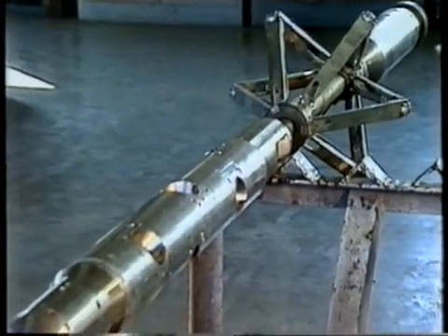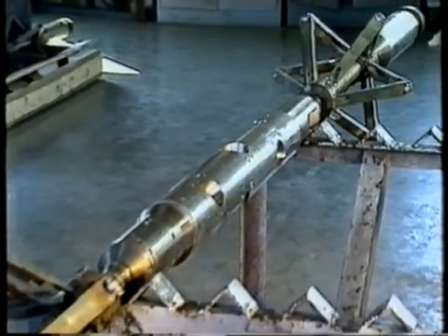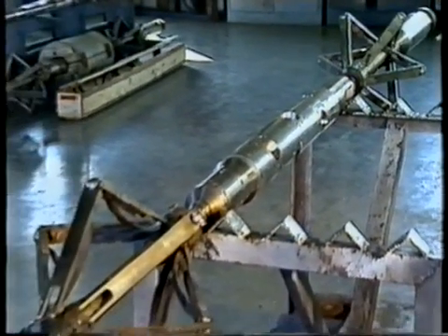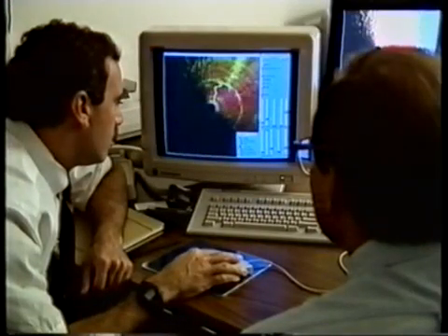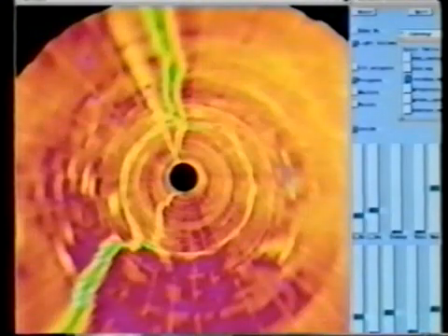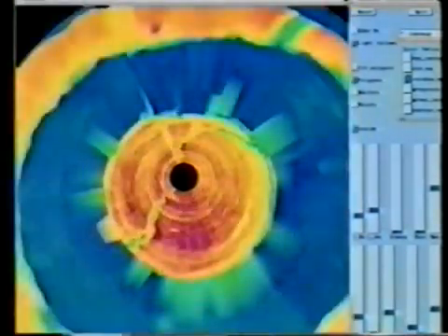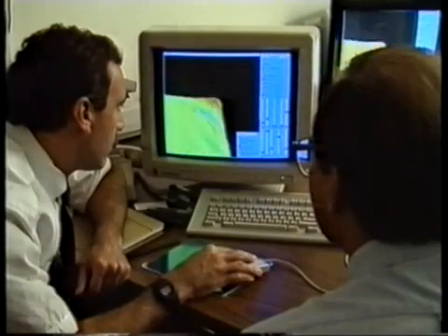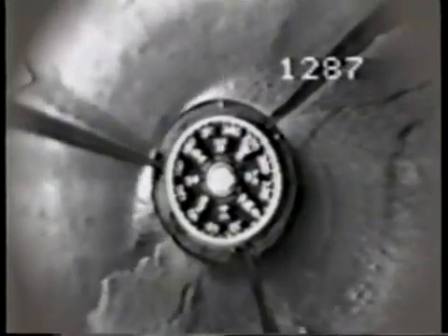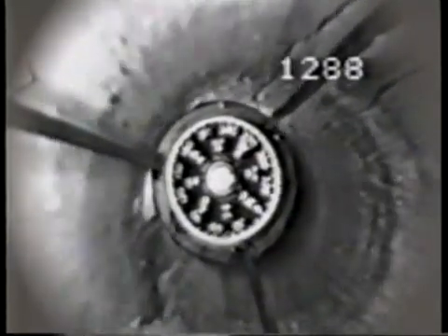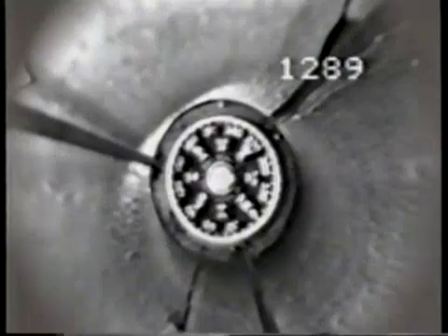The acoustic casing inspection tools, basically modifications of the pulse echo cement bond tools, are discussed in your manual. Also found in your manual is a description of the borehole televiewer, which utilizes an ultrasonic transmitter to produce an image of the borehole or the casing inner wall. These tools require a fluid-filled borehole. Video cameras have also been adapted for downhole use and can provide an image in boreholes filled with air or clear liquids.